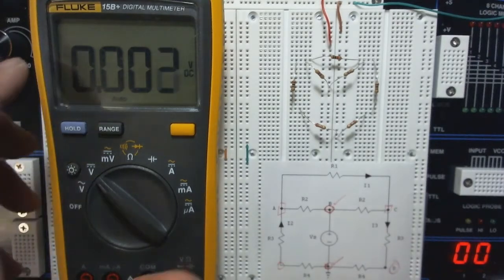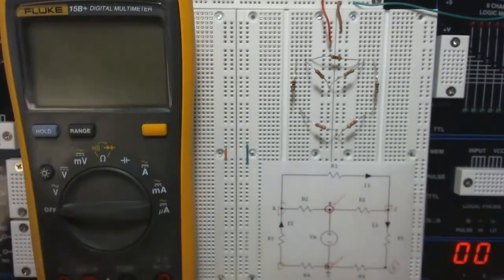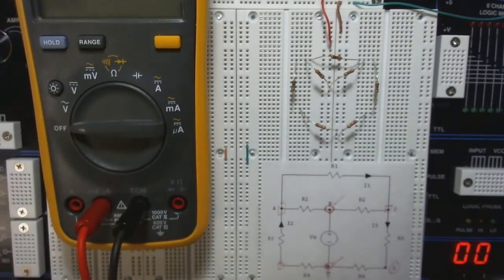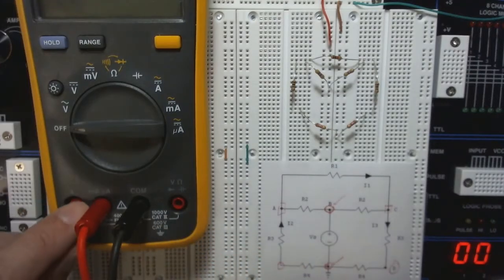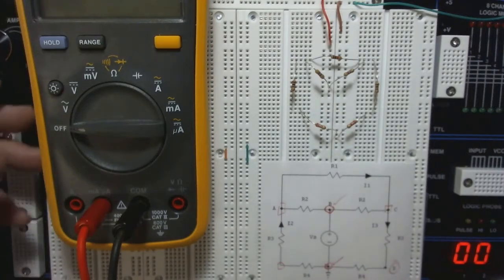Okay, so I'll switch tools on you here, just because I've got this rigged up with slightly different leads. And also when we go to measure current, I switch from over here, where I measure volts and ohms, and I move over here. I'm going to be measuring milliamps and microamps, because you did your calculations, so you should know roughly what the current is, so you know we're not going to be anywhere near 10 amps.